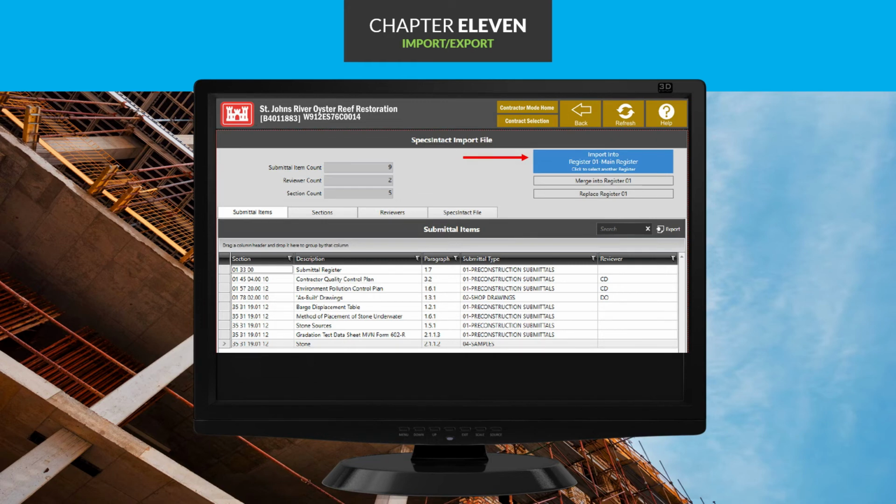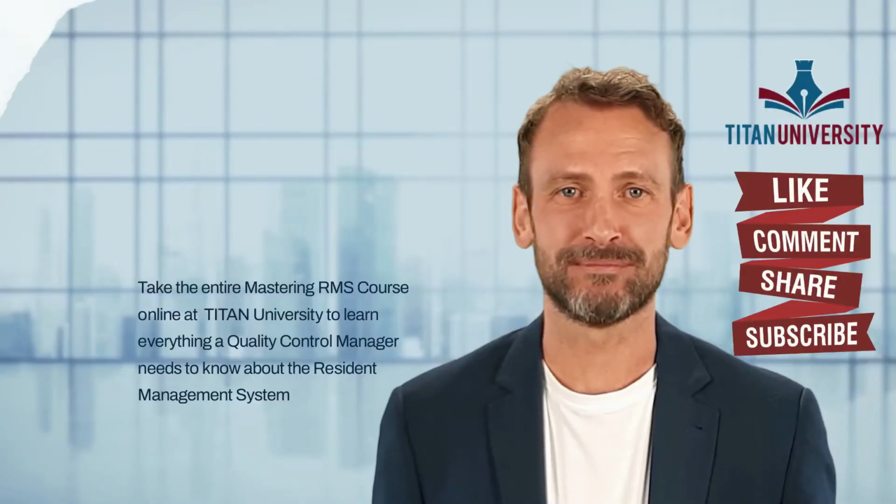Then select whether you want to merge the register or replace the register. When you merge the register, the items will be added to the current submittal register without removing existing items. If you'd like to merge the register, select the button. To replace the register, RMS will completely replace the entire submittal register, including items that may already have been transmitted. If you proceed to replace, you will be prompted to identify yourself. The username of the logged-in person will be displayed. Enter the password belonging to this person, then click on OK. A log of these types.